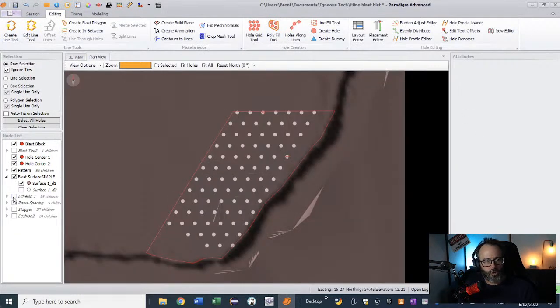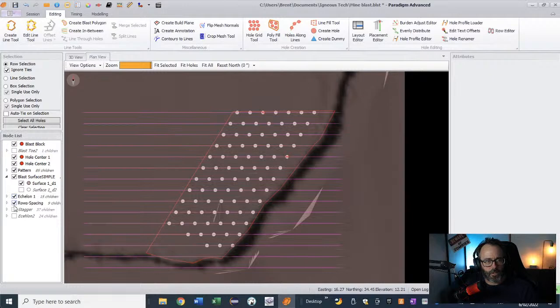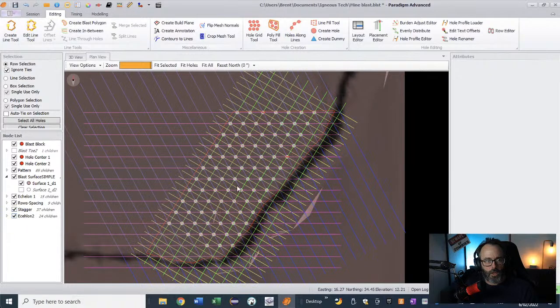But what I want to show you is this concept of gridding, so that you can find out where to put an appropriate blast hole for an infill, if you're just doing a mine blast, or where you can move a blast hole to. This is quite complex in terms of what you're seeing on the screen, lots of lines. So I might show you it in my program that I wrote called LiteTie.